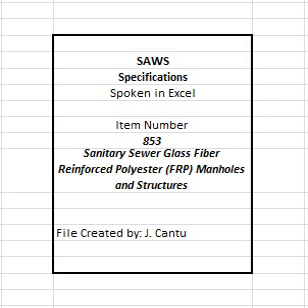5. Class. Manholes shall be manufactured in one class of load rating. This class shall be AASHTO H20 wheel load. 6. Manhole bottom. Manholes and structures are required to have a resin fiber reinforced bottom.